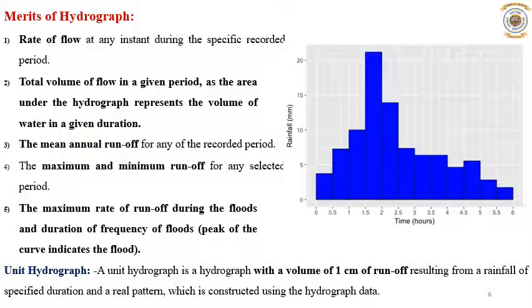So it is possible to predict a runoff hydrograph corresponding to an observed or hypothetical storm. The basic concept of unit hydrograph is that hydrographs of runoff from two identical storms would be the same. In practice, identical storms occur very rarely, but the rainfall generally varies in duration, amount, and areal distribution. So this makes it necessary to construct a typical hydrograph for a basin, which could be used as a unit of measurement of runoff.